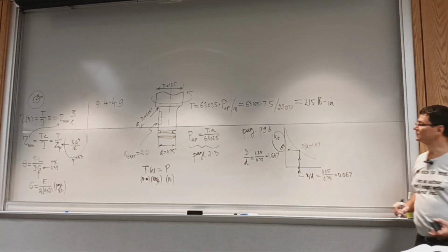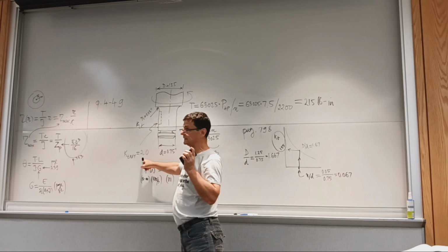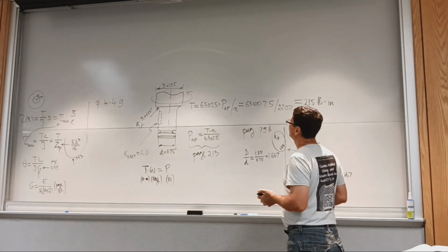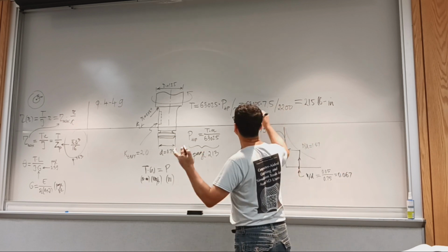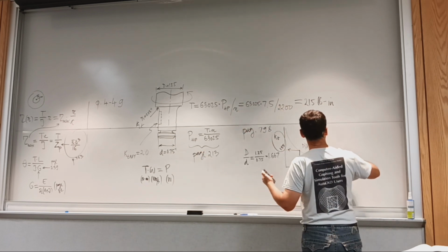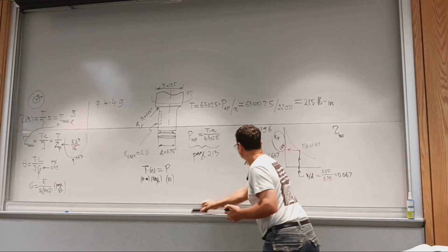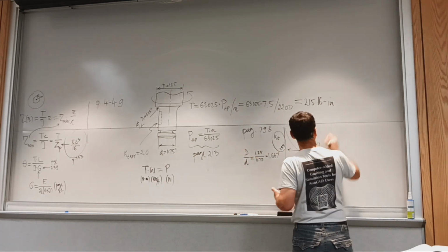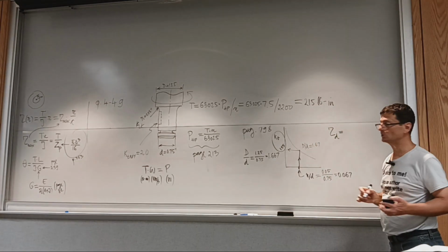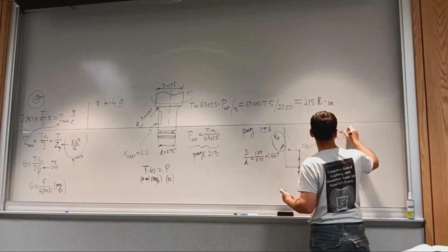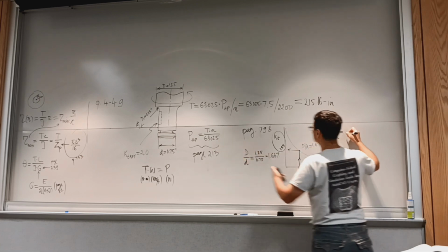Okay, so we've got the stress concentration factor, which happens to be less than for the key. So tau max now, again, this is not a sliding board. I'll switch to sliding board. So tau max, or rather maybe say design stress, tau D, design shear stress, is going to be the biggest of the two stress concentration factors, and that's clearly going to be the one due to the key.